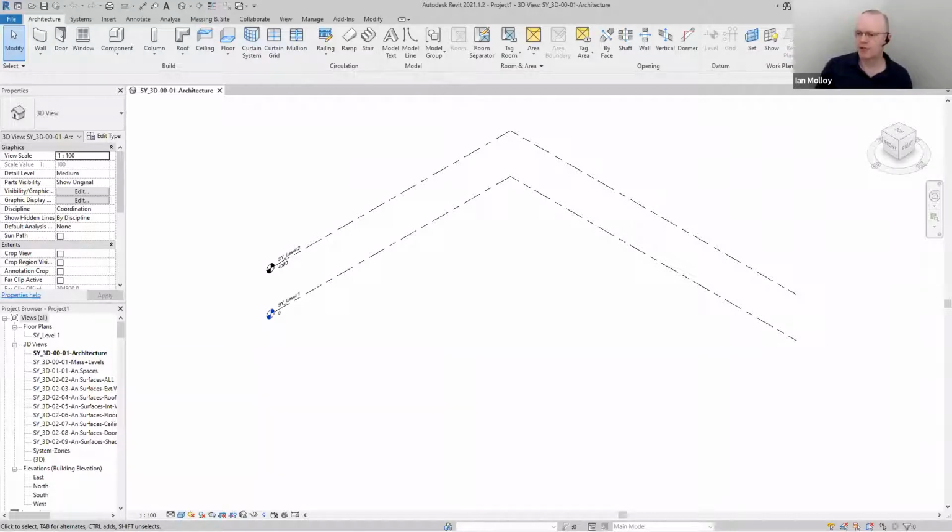Will Insight take neighboring buildings into account? Yes, basically you can do it a couple of ways. Model your building. Any surrounding massing that doesn't have what we call mass floors enabled will be seen as surrounding buildings and provide shading on the building, or even any building elements that are not set as part of the building will do that. So yes.